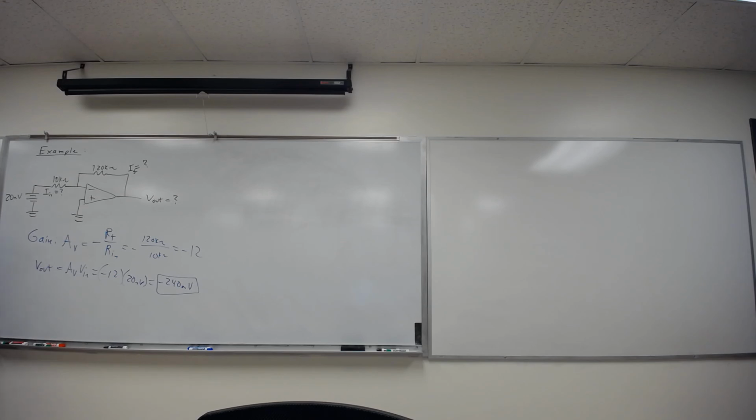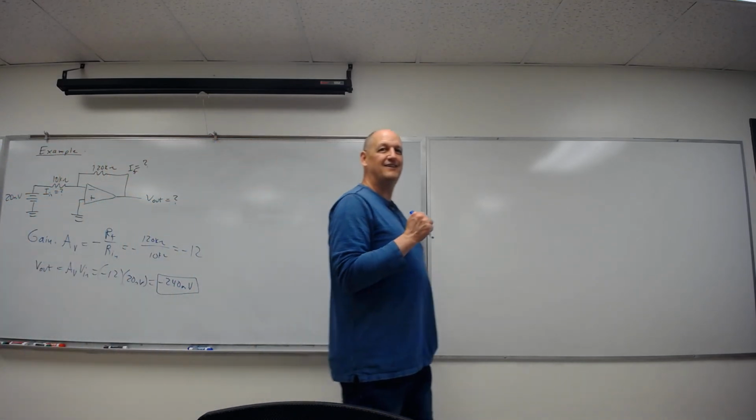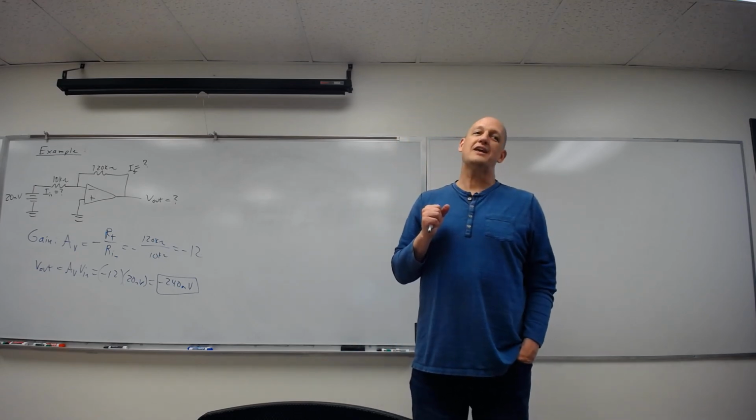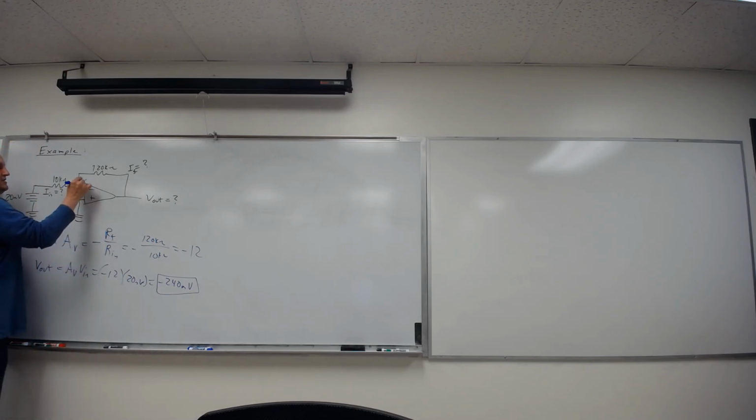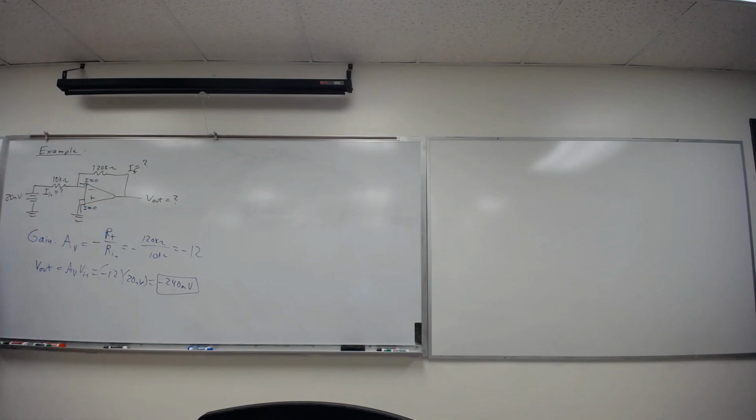Let's start with my assumptions. We had 2 assumptions we said we can make on all op amps. What were those? I laid them all out, I wrote them in detail on the board, and we used them to solve them. I'm pushing this to make sure that you look back at your notes. The first is that input currents are less than or equal to 0. Yeah, they can't be less than, they're just 0. So our input currents here, I'll make it an approximate, but remember, how small are these? Somewhere down in the nanoamps probably, because the input impedance is extremely high in my op amp.